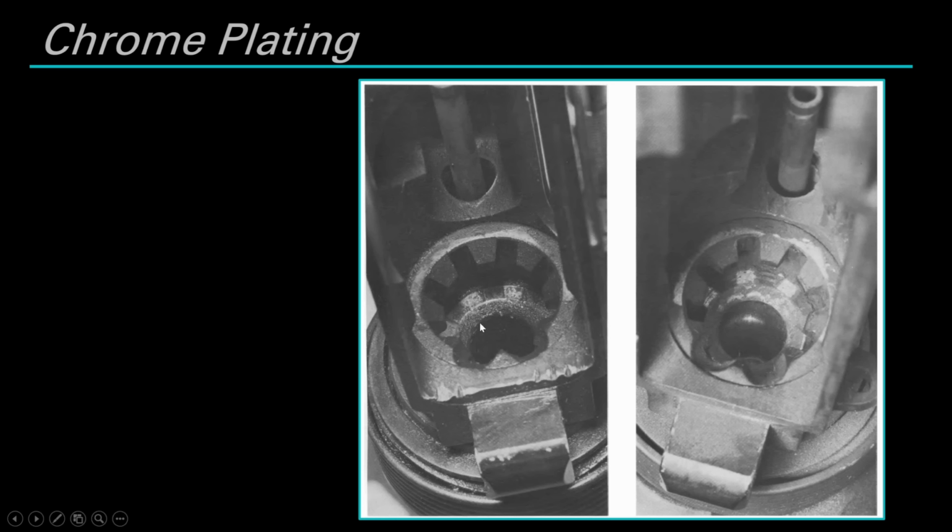Another thing to pay attention to for the rifle here on the left is this series of marks down here at the bottom of the upper receiver. In my opinion, these marks are evidence of somebody sticking something like a screwdriver or some other tool up into the chamber area trying to pry out a stuck case. Because, as we'll elaborate on more later, a badly pitted and badly corroded chamber will lead to a case that gets stuck in the chamber after the round is fired.